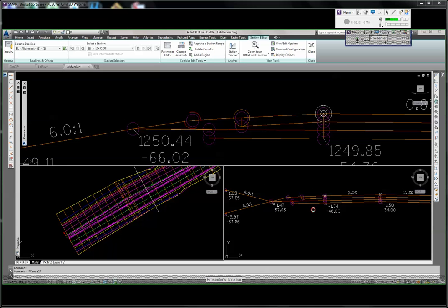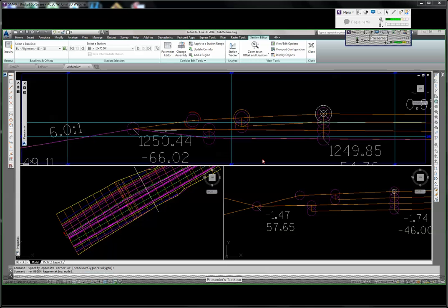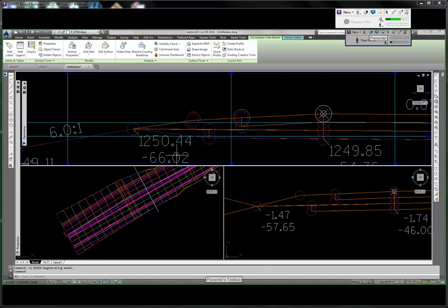Now I'm going to zoom over to the left-hand side here where we have a select sub-base shoulder. Zoom in on both of those there. And you'll see there, when I reach on my screen, that the surface does the same thing. It comes up from the daylight on this side, gets to this point, jumps down to this one here, and continues on. This link here is vertical, by default, and therefore it doesn't cruise over there.